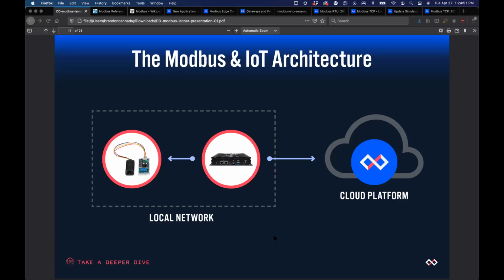A very easy way to IoT enable that equipment is to do a retrofit and introduce a small gateway into that enclosure. It's directly connected to the controller, and through cellular or whatever internet connectivity it can get, it can still make that outbound connection to the cloud. So the local network describes either a facility or a building, and it can also describe what happens inside a piece of equipment itself.